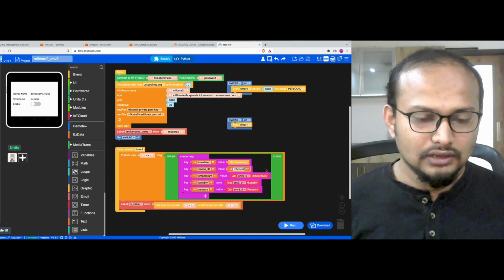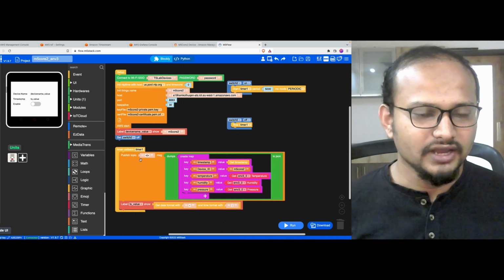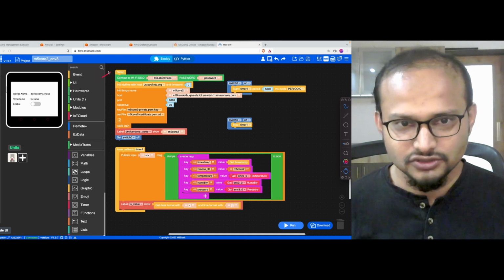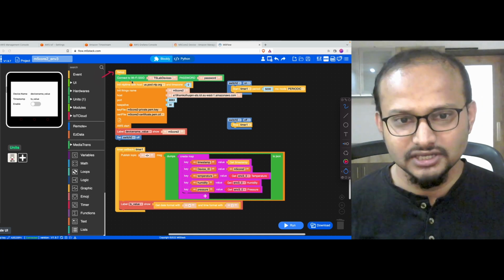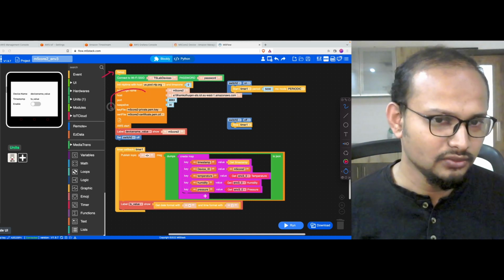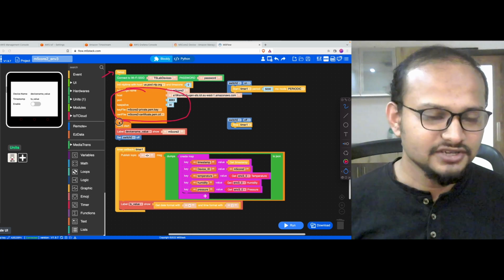Okay. And what topic should it be publishing to? Let's quickly go through what happens in the program. This is the first thing that gets executed, the setup, and then it tries to connect to Wi-Fi, connect to the time server, and set things up so it can connect to AWS IoT Core. Then when we say AWS start, this is where it actually establishes the connection with AWS.